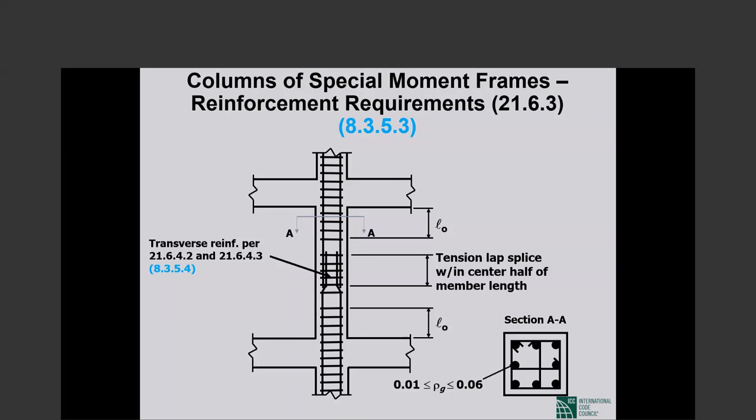The 3% is way high. I discussed that. I remember 3% reinforcement in a column. You can place the reinforcement, but the problem is, you have to think of the beam column joint, and let us try to visualize it. Okay, the beam column joint has the column bars going through.